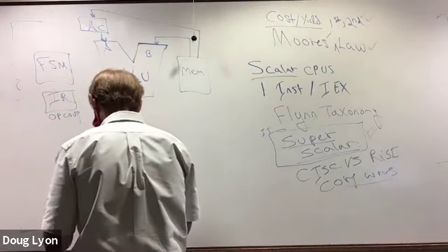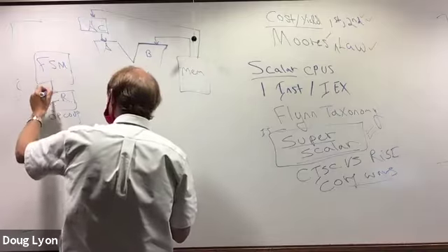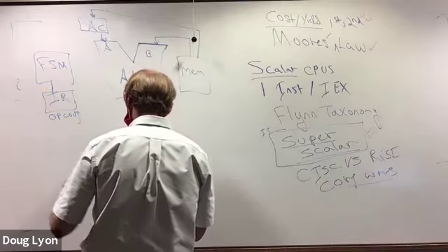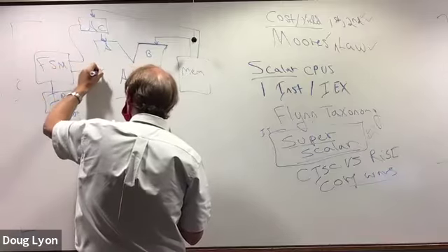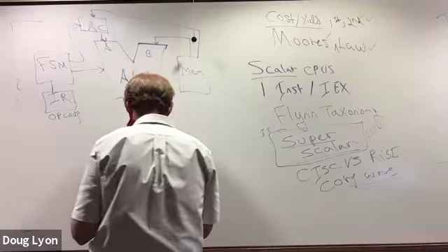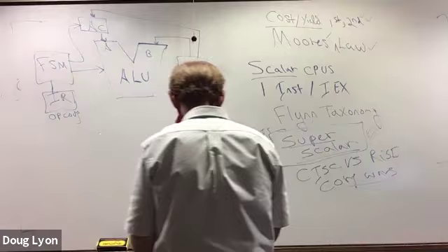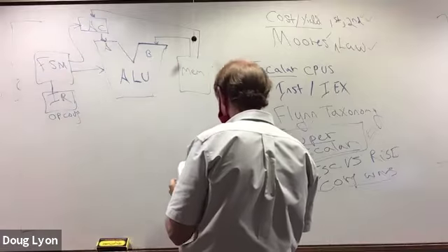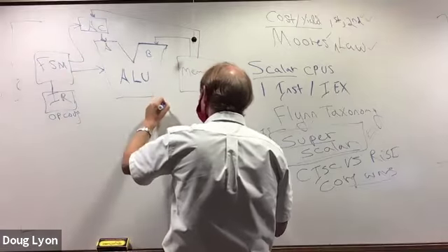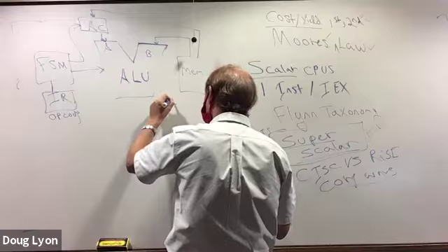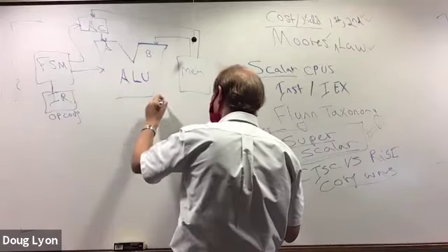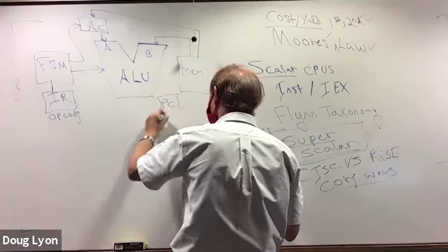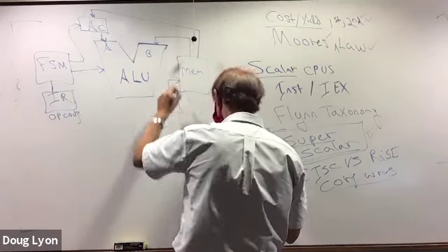This basic architecture is going to feed the finite state machine, which will determine what it does with the accumulator, the ALU, and somewhere in here we'd like to have a memory address register, also known as the program counter. I'm going to use program counter, that's okay. They're interchangeable. So here's the program counter, and that shows us where we are in memory.